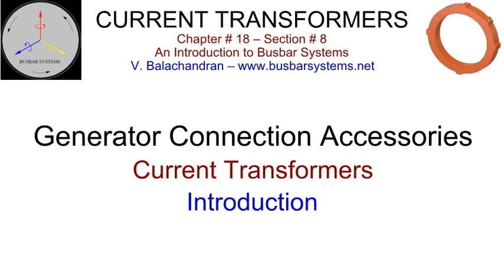Generator connection accessories. Current transformers. Current transformers are installed in the generator connections for metering, protection, and control. The specifications for the current transformers, their assigned location, and sequence in generator connection are finalized by the project authorities based on system parameters, protection philosophy, layout, and relay characteristics.